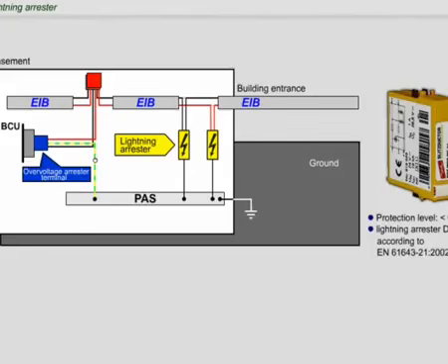The first bus device in the building has to be connected to a special blue overvoltage arrestor terminal for secondary protection. In the following, this terminal is described in more detail. The distance between lightning arrestor and this terminal should be a few meters.